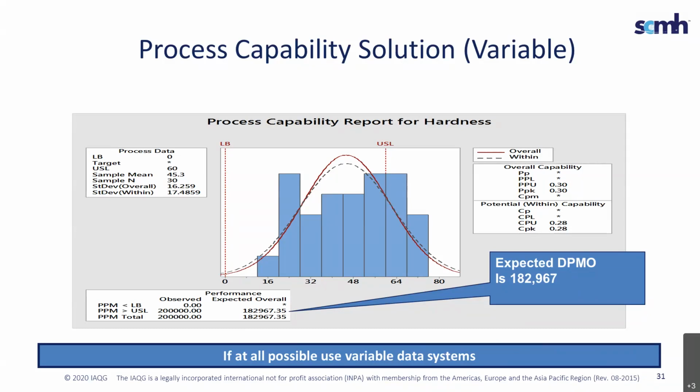And when you're calculating those indices to start with, just bear in mind that it's going to take a while before you can report a true stability or CpK. So time is your friend, or you go to 100% sampling so you can get enough data points to start charting that. Again, making sure that you have the variation accounted for. What I've done in the past sometimes when I've had this problem is that I start with my 20 samples, I do 100% sampling, and then I just make sure as I add more lots and sample sizes that it seems to fit within that and no special cause variation is popping out at me.